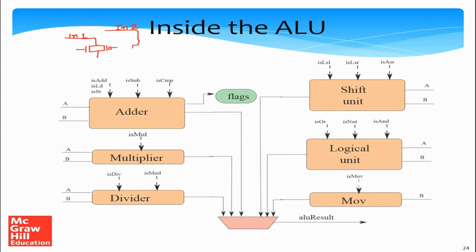So let's have two transistors back to back. And let this be the output line. And so let the signal that's controlling this be A, and let this be the complement of A, which means both are enabled. Similarly, let this be B and the complement of B. So this structure over here is called a transmission gate.